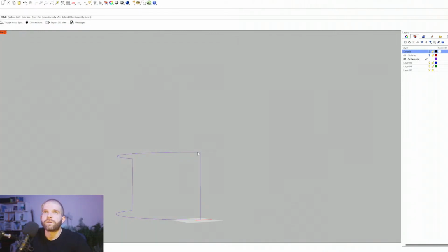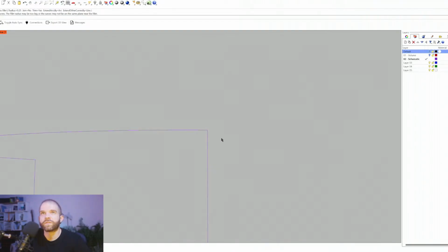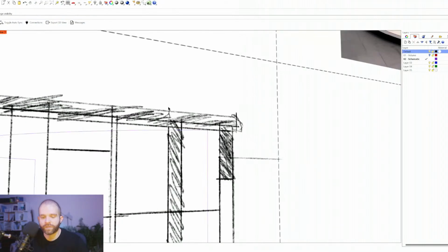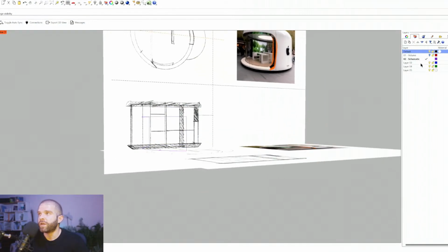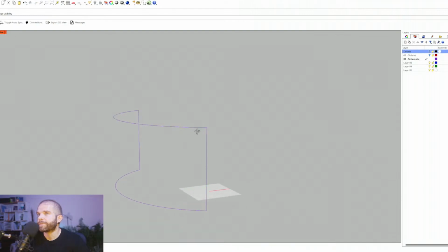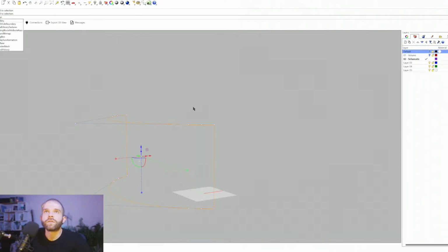All right, and then we set a radius. So I'm first going to select here. I think the radius was way too small. Oh, unable to fillet the curves. The fillet may be too big. The curves may not be on the same plane near the fillet. Well, they're not, definitely. Let's see. I might have to turn this into a surface. Let's see if we do boundary.